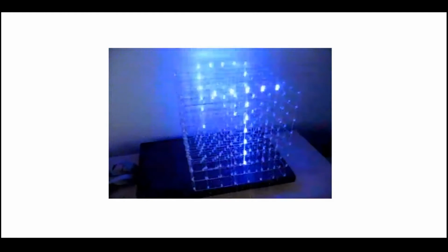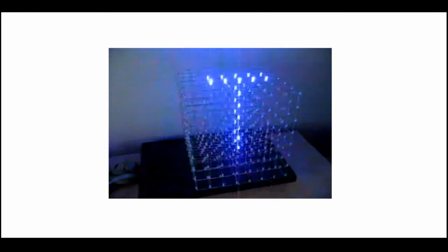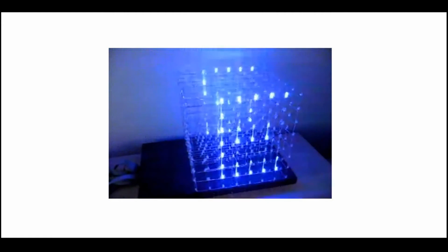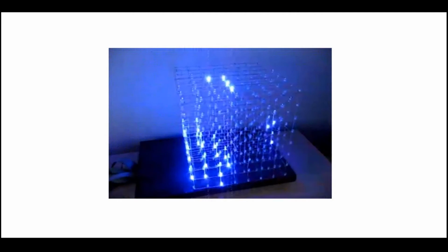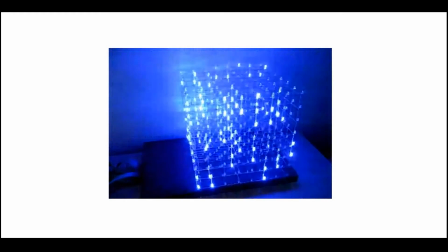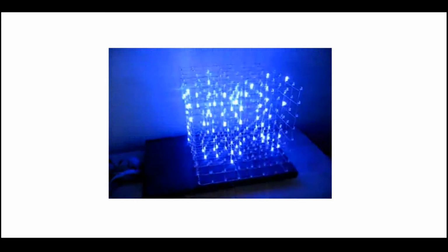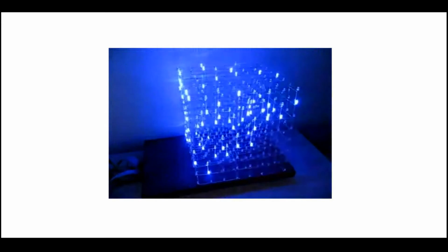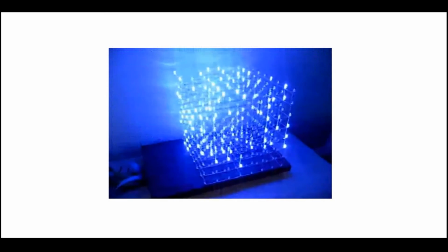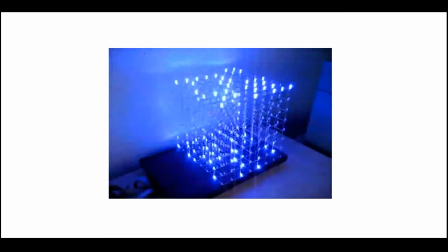If you consider an 8 cross 8 cross 8 cube, it's 8 into 8 into 8 pins, right? Unfortunately, it outnumbers the IO pins that any microcontroller will have. That's one problem. We should solve that problem.